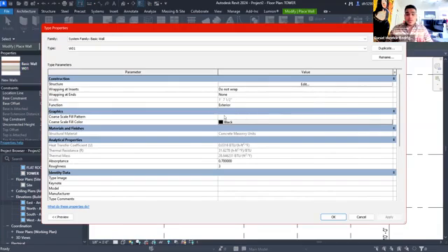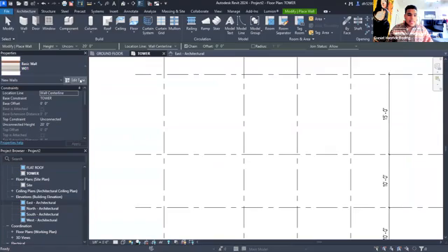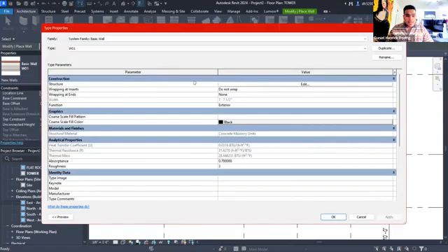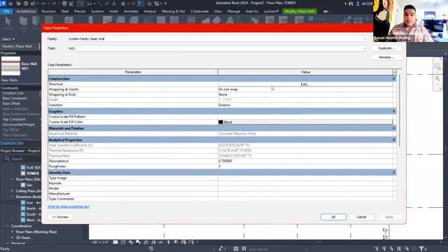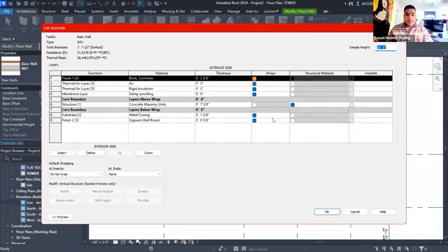Okay, so I just want to show you guys how to change at least one thing about this wall. Whenever you click on Edit Type, you're going to be able to access all these different properties, but we're going to change one of the structure values. So we're going to hit Edit, and this is essentially the wall if you were to cut it and look at it from up top. If you look on the top part here, it says exterior. Here it says interior. So if we take a peek, the wall goes from the inside out.